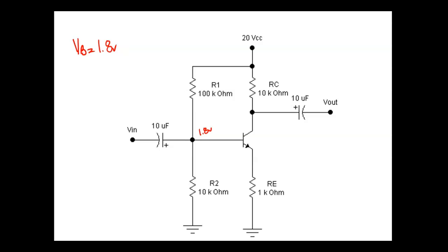Everybody okay? Anybody want to see how Mario got that? Nobody saying anything. How do you get 1.8? Well, we have a couple of ways we can do it. I can say it's a series circuit. We're calculating the volts you drop. R2 sets the base voltage.